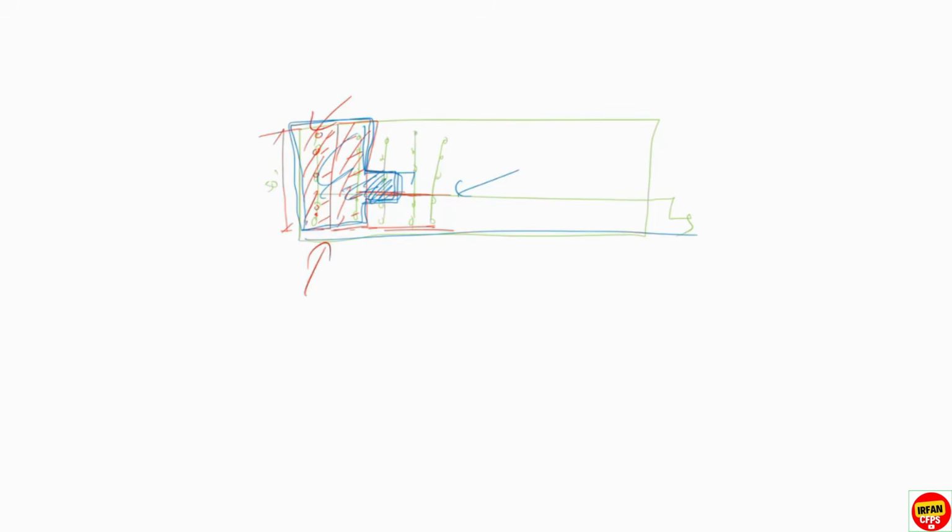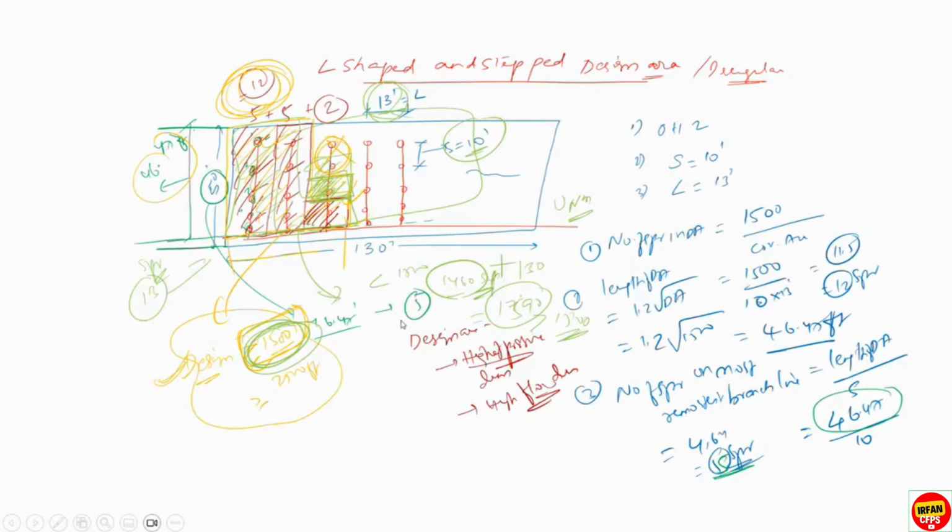Okay, so let's move ahead then, if there is no doubt. Now the next topic will be design area validation. As I told you in the previous slide, you need to make sure that whatever design area you get in actual as per the drawing should be more than the minimum design area requirement based on the hazard occupancy.